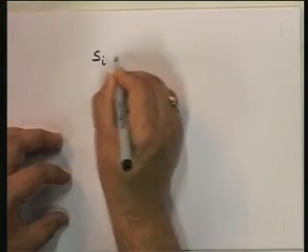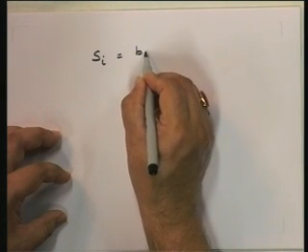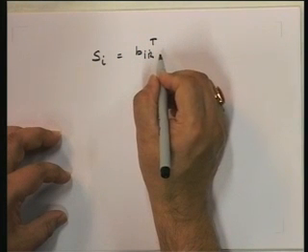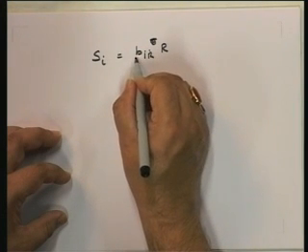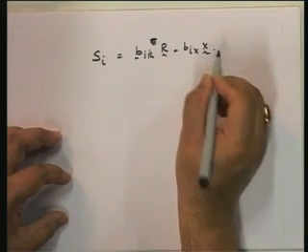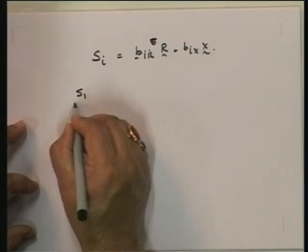Once you found out your sway, the next step is finding out the rotations, right? And if you look at the member end forces, the member end forces will be given by S_i is equal to S_iR plus S_iX. Okay, so let us look at S1.